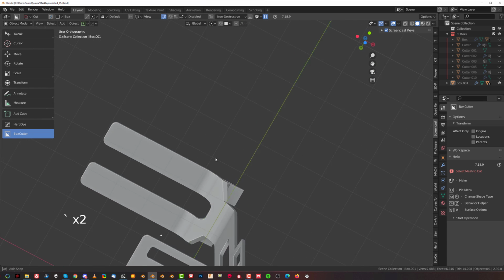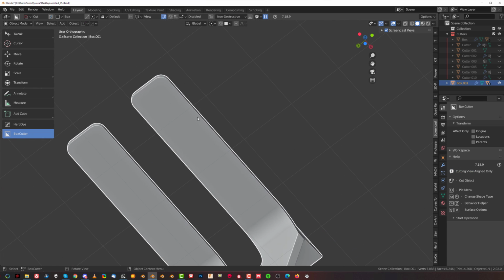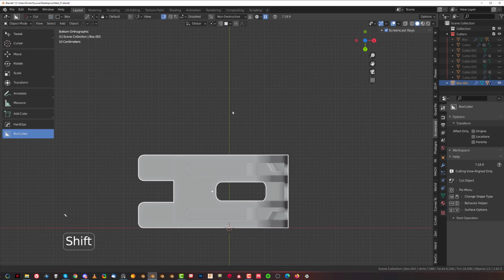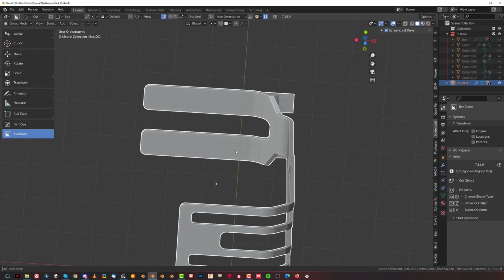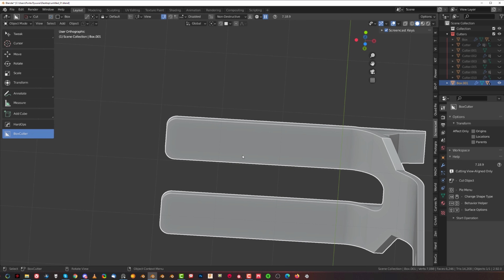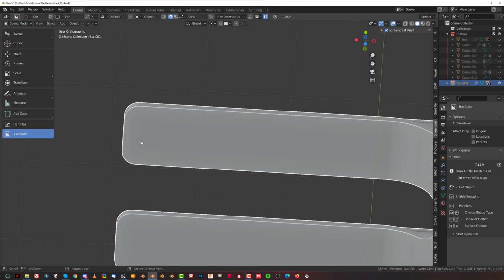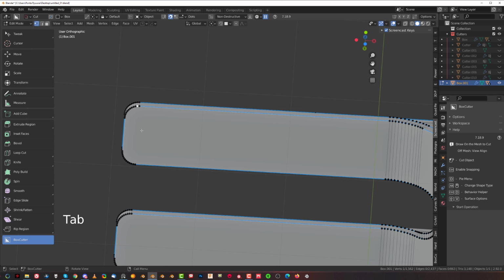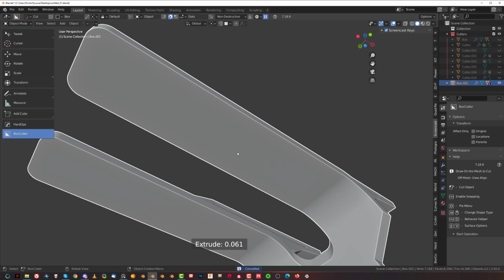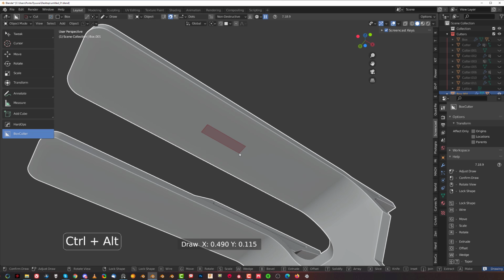Now on the bottom here, what we need is a cutter. But you see, if you're gonna go to the bottom, you can't really see it because this base is obstructing our view. So we can switch here to object to draw in object mode. Go to this magnet, which will allow us to enable dots when we hold Control. And we're going to draw a line here, right? Press J. Now what we can do is hold Control, click and draw a shape here, hold Alt, and now you can draw it in the middle, see?